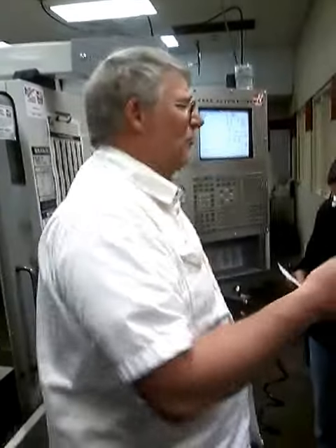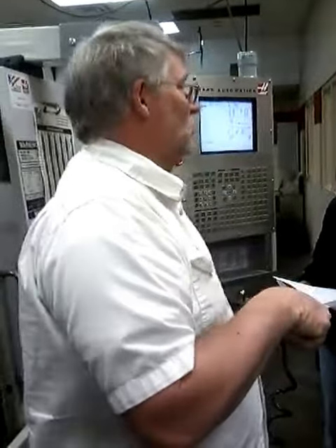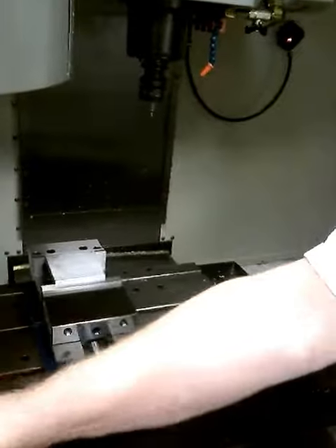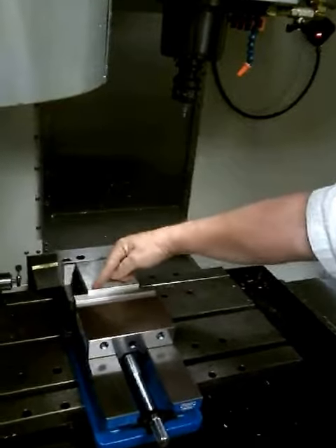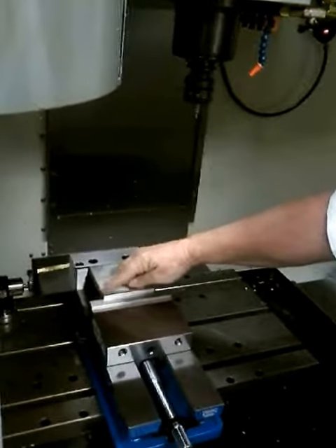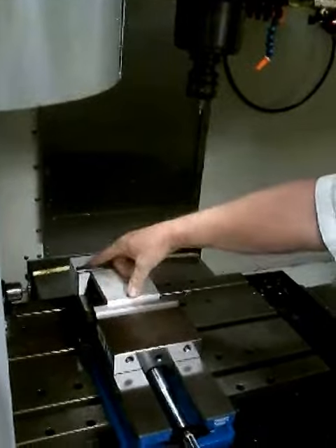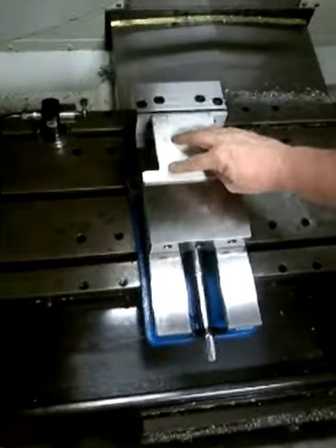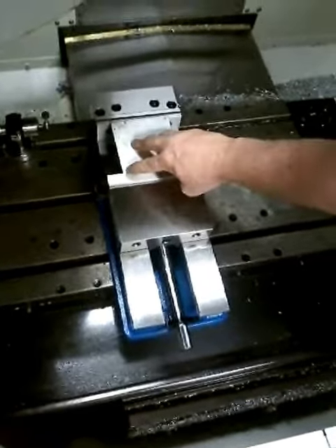I could be using a half round, I could use an end mill. I'm good enough I could use a center drill and just eyeball it sometimes. Okay? We're going to do it accurately, and we're going to do it with an edge finder today. So I've got the edge finder installed into the spindle. For practical purposes, so everybody can see what I'm doing, I'm going to pick on the front left corner instead of the back left corner, just because it's easier for everybody to see. And I can put it anywhere I want, right?